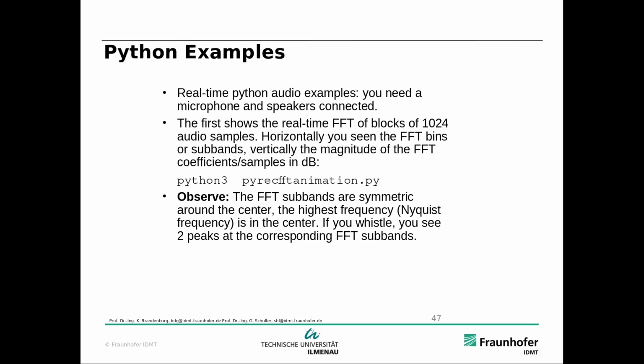Yeah, and here are some Python examples on the principle of the subband decomposition. So real-time Python audio examples. Here we need a microphone and speakers connected. And the first shows a real-time FFT of blocks of 1024 audio samples. Horizontally, you can see the FFT bins or subbands. Vertically, the magnitude of the FFT coefficients or samples in dB. So here, this shows the real-time animation of my microphone signal.